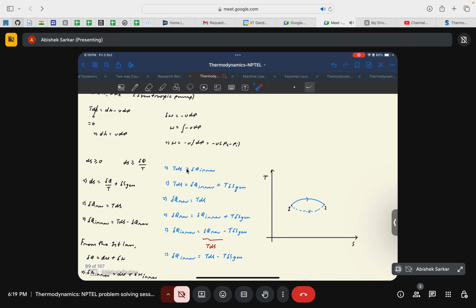Now since the change in the specific volume of the fluid is in general very small, almost negligible, we can take the specific volume out of the integral and just integrate the change in the pressure. So we're left with the work done from a pump equal to minus V times (P minus Pi). This is the expression in general that we use to find the net work input to the pump when we consider these Rankine cycles or steam cycles.